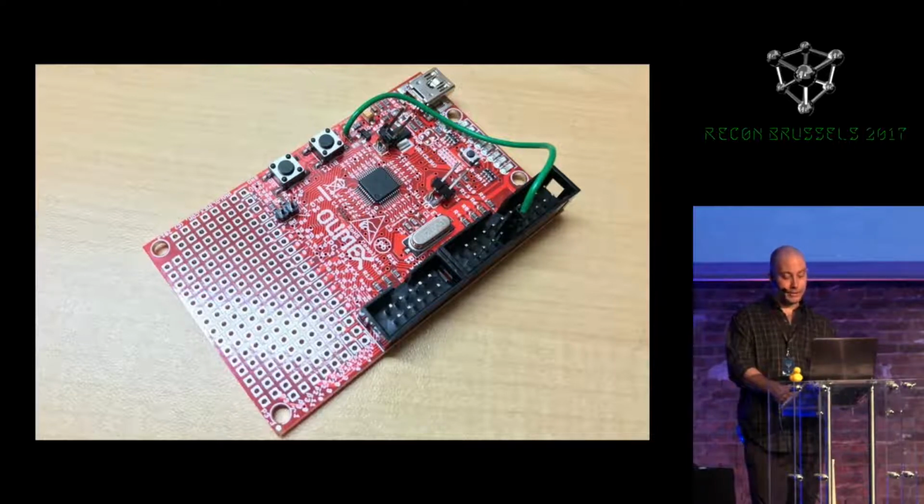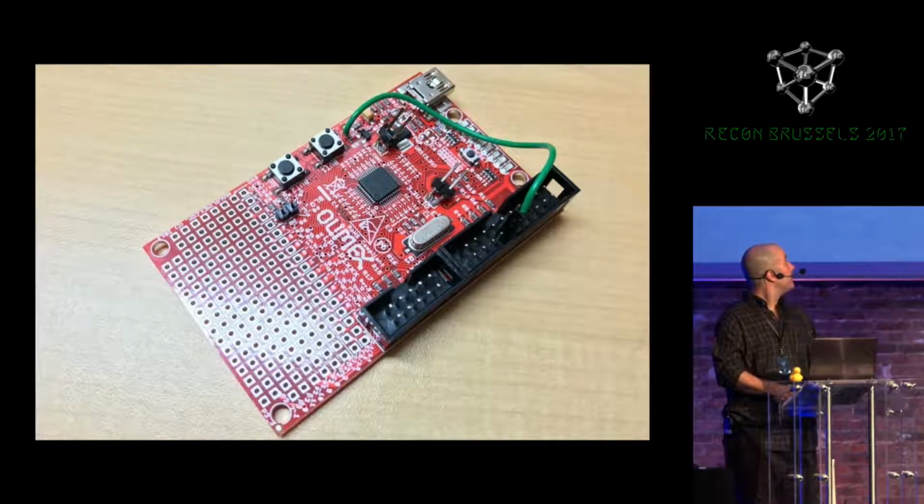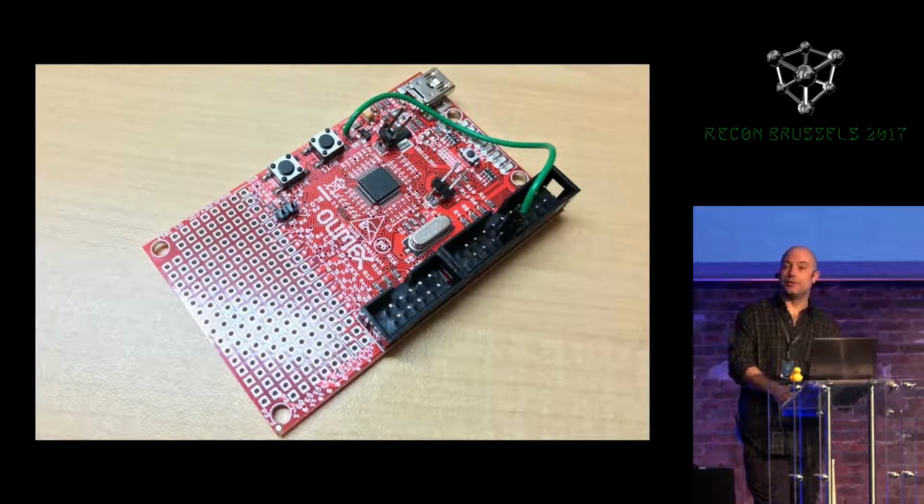Also, I've cut 2 traces on the board, which are for the VDD and VDD I/O signals. This development board is set up nicely in that they give you a spot specifically to cut if you want to disable the power supply from the board. So I've installed jumpers on those locations so I can connect with my own power connection. And then also I've added this green wire, and this green wire is just connected between the ground pin on the debug port and the VBus signal going into the chip, because normally this development board is designed so that you'll be using the USB bootloader. So in order to disable the USB bootloader, I've added this green wire, which is simply holding the VBus pin low. So we'll enter the serial bootloader instead.